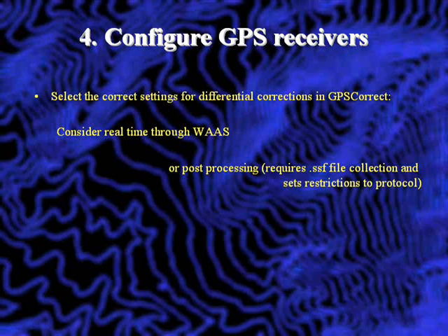So yes, ArcPad will run on other handhelds as well, but one of the disadvantages is that you cannot select to collect SSF files, which are required for post-processing. But make sure that you configure the GPS receiver to collect whatever you want, either real-time WAAS or post-processing.